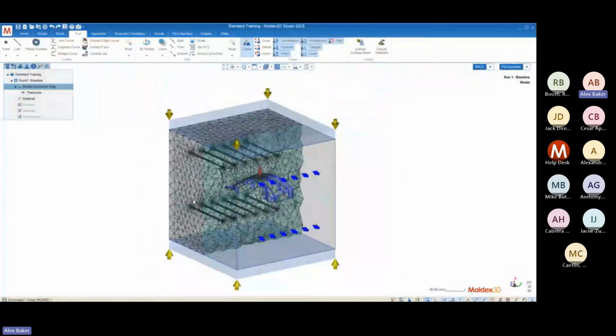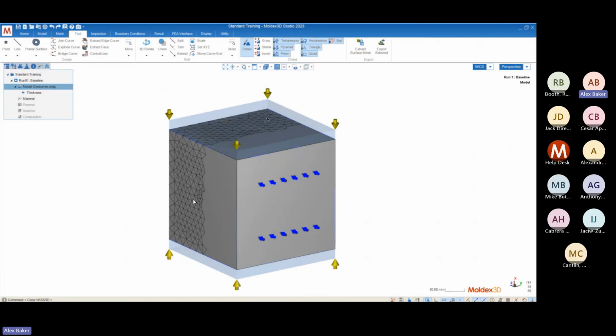Using the toolbar up at the top middle of your modeling window, right underneath the chisel function, there's this toolbar right here. The middlemost button on this toolbar, which looks like a little orthographic cube, and the first button allows you to see the mesh if you don't already see that. The last button in this toolbar allows you to turn off the transparency of the mold.